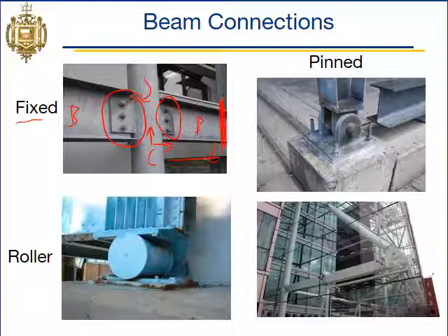Here's a good pinned connection. This column here is pinned to the foundation system, so it can resist these lateral forces. The thing's not going to just come flying off. Obviously, the foundation is resisting a y direction force, keeping it from just sinking into the ground.